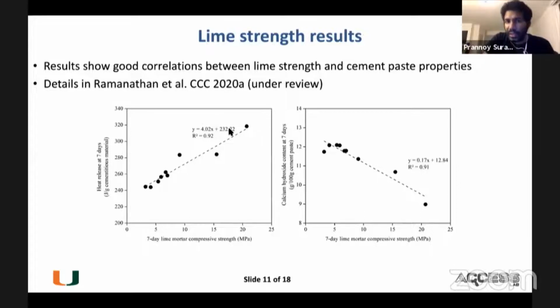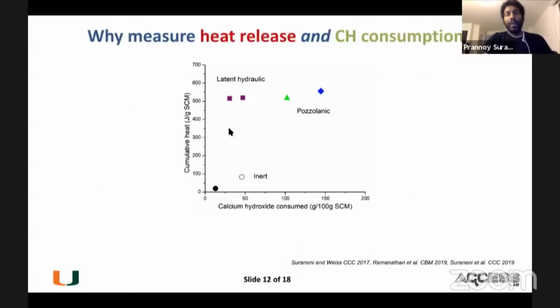Now, both these tests, the lime strength and the R3, are measures of total reactivity. They do not differentiate between pozzolanic and hydraulic reactivity. Now, what we do in my research group is that we measure both the heat release and the calcium hydroxide